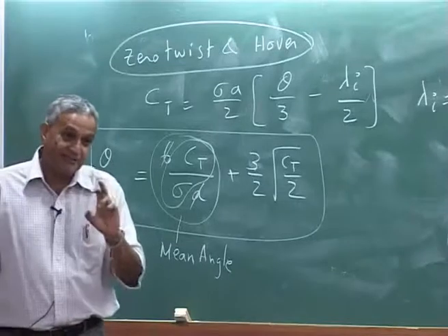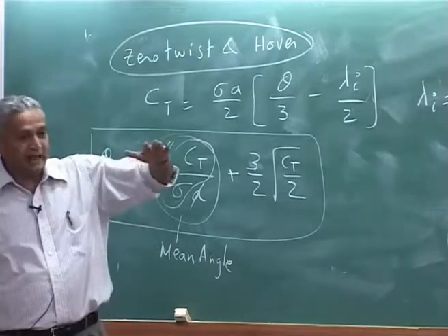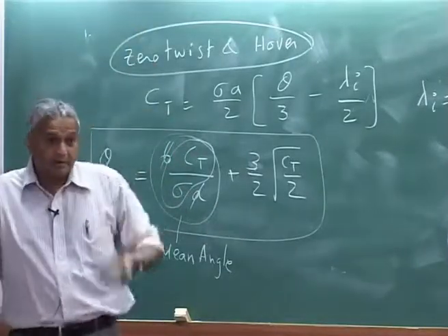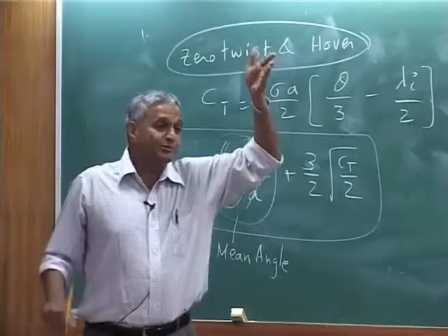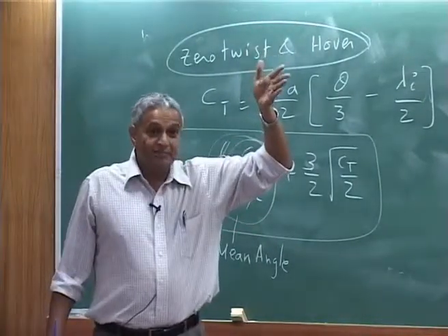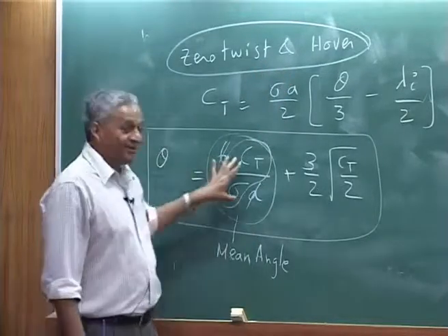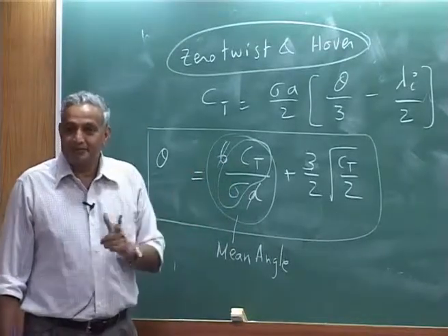So, these are very important. If you are near the stall angle and you want to climb up, because this is for hover, I have to increase my thrust, I increase my collective, but you will not be able to lift, the blade will stall. So, this is very, very important, Ct over sigma as a parameter.